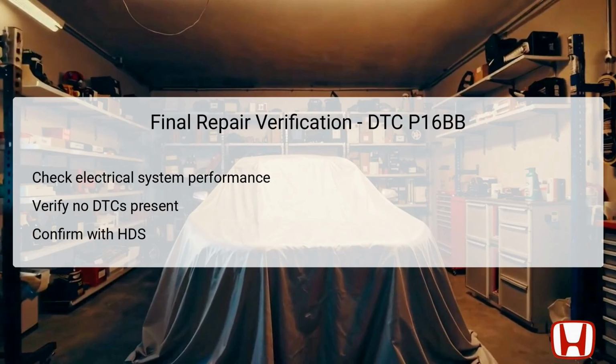Final repair verification is critical to ensure that the issues leading to DTC P16BB have been effectively resolved. Begin by checking the overall performance of the electrical system, making sure that all components function as intended under normal operating conditions. This can involve testing systems such as lighting, AC performance, and other electrical components that were symptomatic prior to repair. Post-repair, the vehicle should be re-evaluated with the Honda Diagnostic System, HDS, to confirm that no new or recurring diagnostic trouble codes are present.